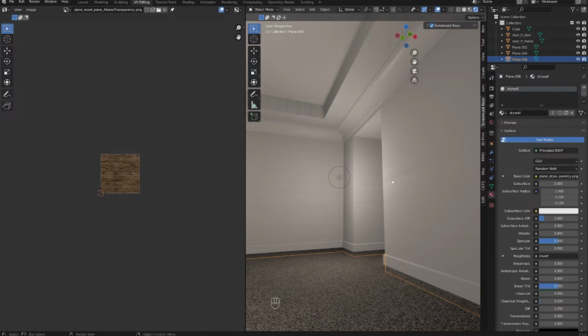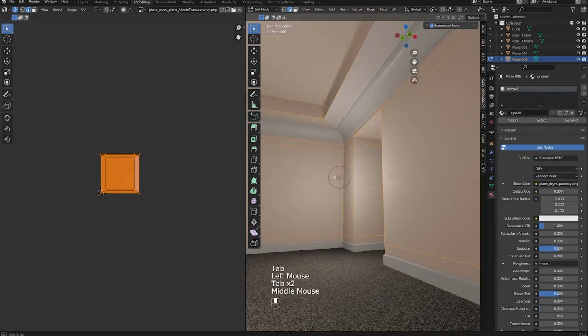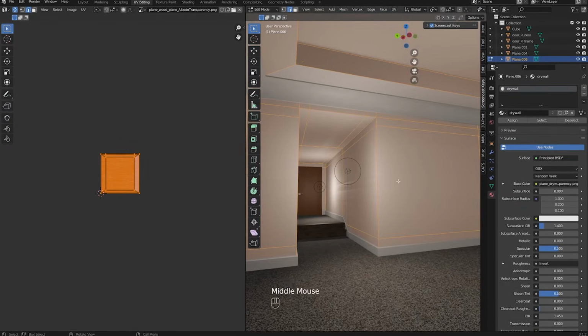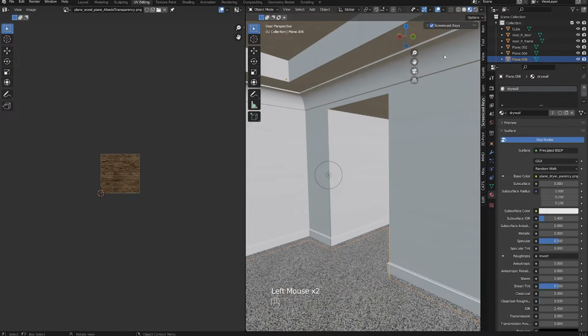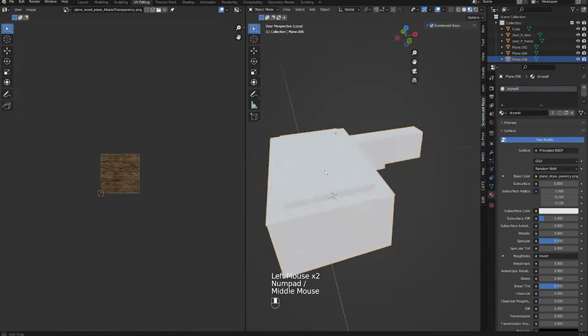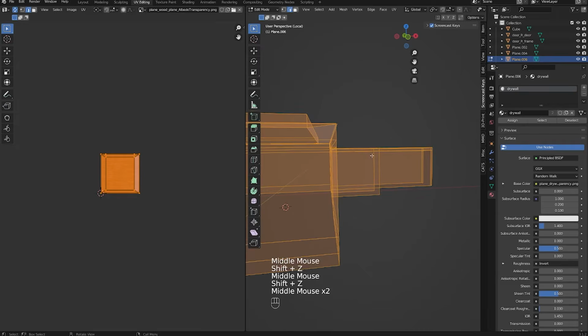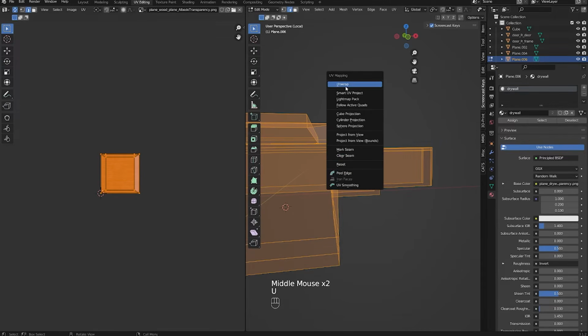And since this is a seamless texture, and I'm going to be scaling the object on the 2D plane, I'm going to be scaling the object in the UVs. I want them to be the same. Let's go back to the material view. Let's do / on the number pad. Let's just select everything and try to unwrap this, and you can kind of see what happens.